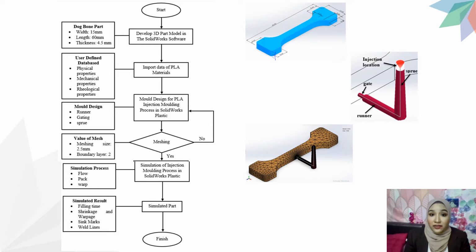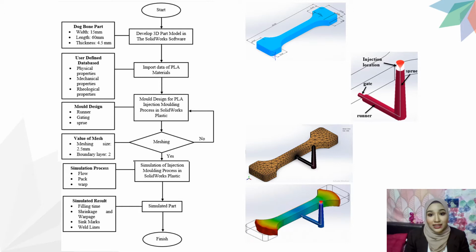Lastly, the final result was analyzed and identified from the simulated part, focusing on the filling time of the cavity, shrinkage, warpage, seam marks, and weld lines. This result is crucial for studying the flow behavior of the plastic materials and for future research studies.